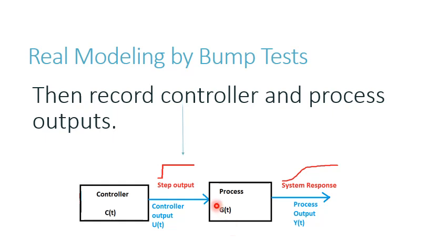Well, the next step is you're going to record. You're going to record your controller output. Here is the step, and you're also going to record the process output. So it looks like this in this case.